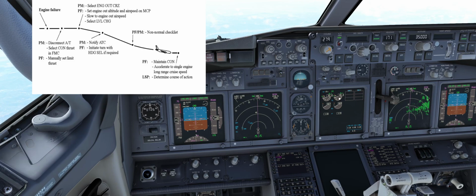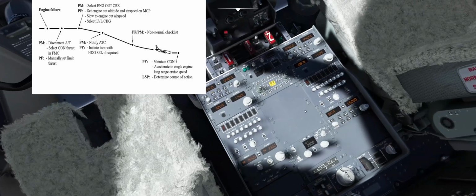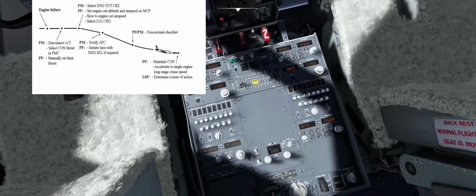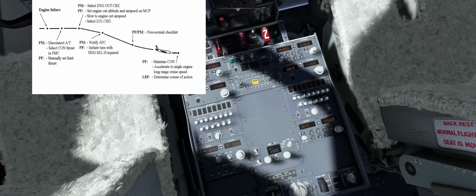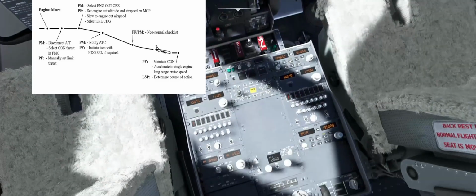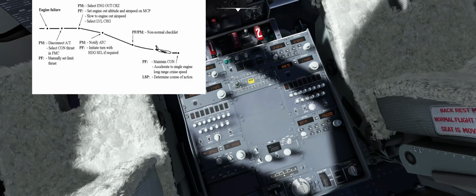Basically, if you have full thrust on one engine, and you would like to equalize the forces on your rudder, the more or less you need to put in rudder trim. For example, if you lose engine number 1, engine number 2 is working, you have yaw moment and you are drifting to the left, so you need to apply rudder to the right, and the sweet point is approximately 8.